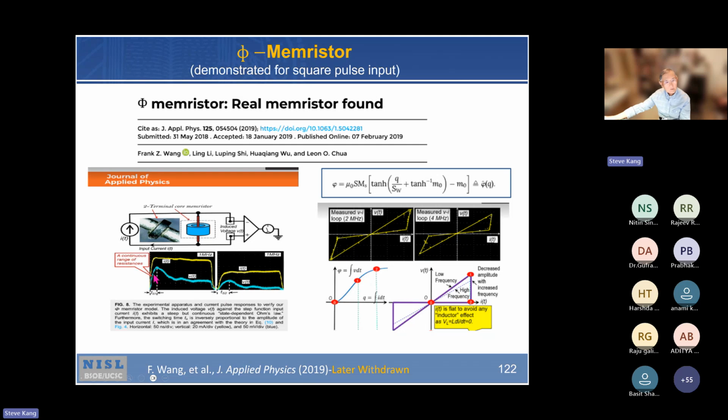So they showed some interesting characteristics. They introduced a model like this. Phi is equal to hyperbolic tangent, and then inverse hyperbolic tangent, etc., which is a function of Q, right? Q is here. So phi is a nonlinear function of Q, so Memristor characteristics. And then they did an I-V measurement, which is rather almost linear here, and then set voltage and reset voltage type of thing, 2 megahertz and 4 megahertz, right?